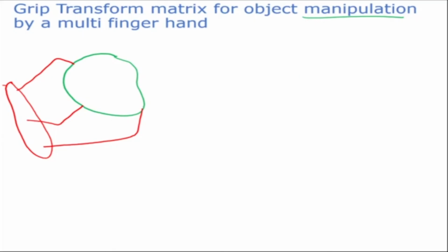Now we are saying that each of these fingertips can apply a force, which is F, or a twist, and a wrench, which is V. So the fingertips can apply a wrench or a twist. Because of these multiple fingers, each of them can apply a twist or a wrench. What will happen is the center of the object will have some motion. Let's say the object is moving like that. There is a sum of forces acting at the CG of the object, and it has some twist.